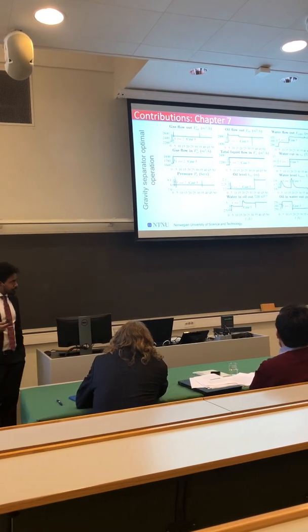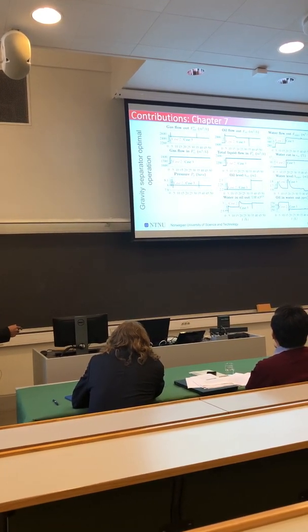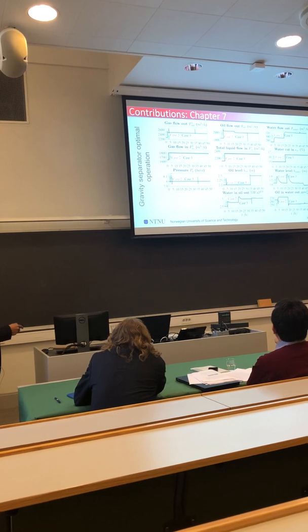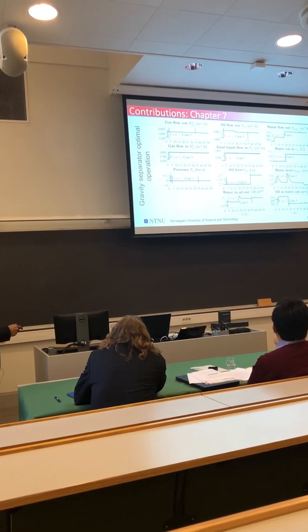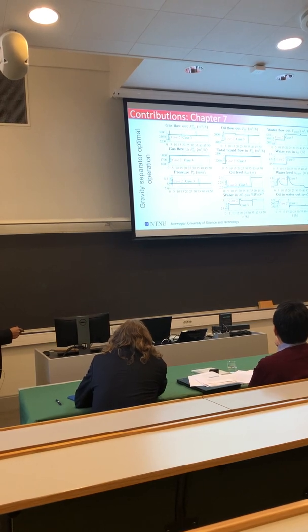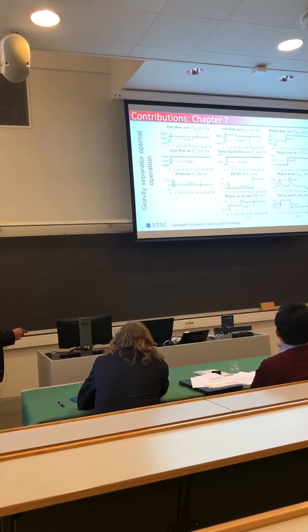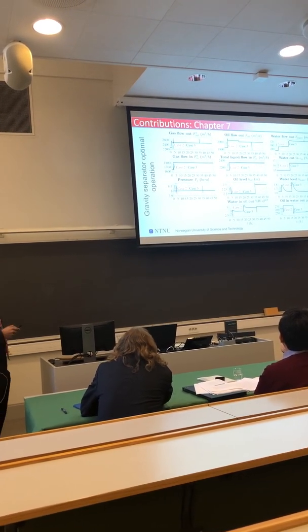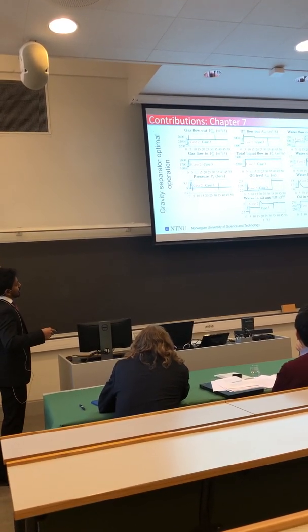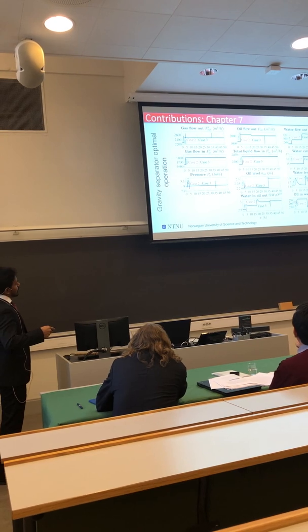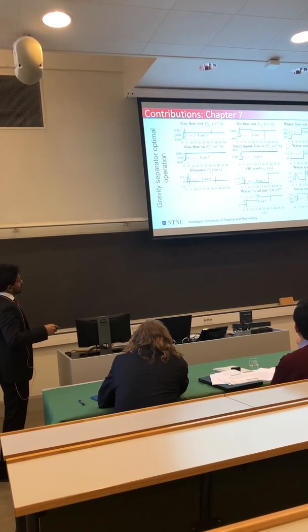We also are able to see the water in oil content and oil in water content, as we can see that the separation load is increasing from case 1 to case 2. That's why the separation gets worse and these numbers become higher, which means they're more impure. The oil in water in ppm goes from 260 to 270, and the same for case number 3.